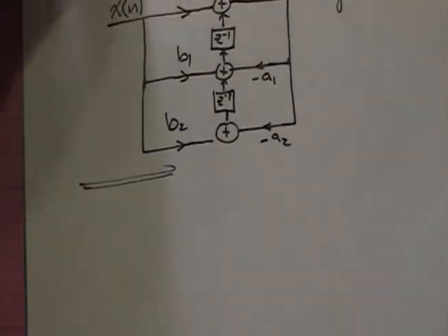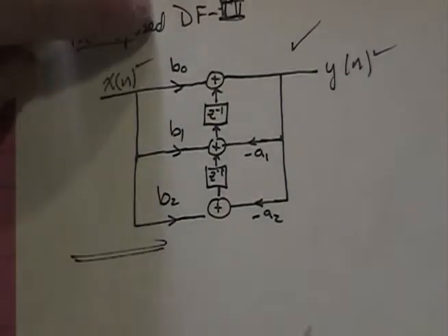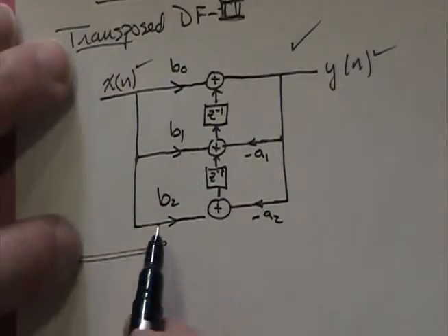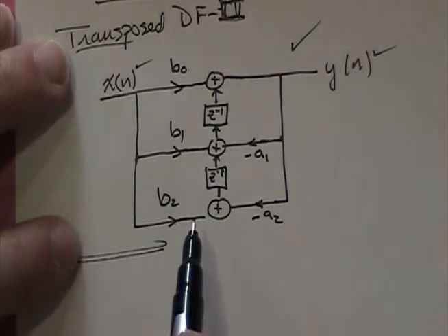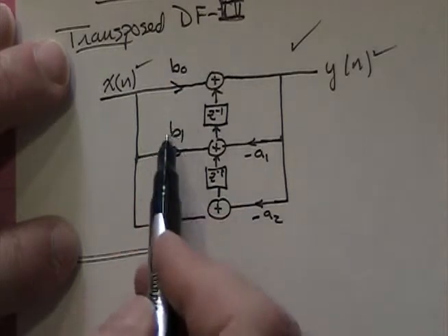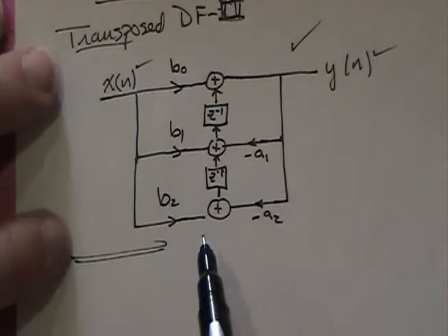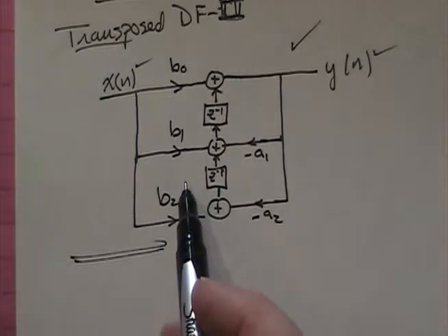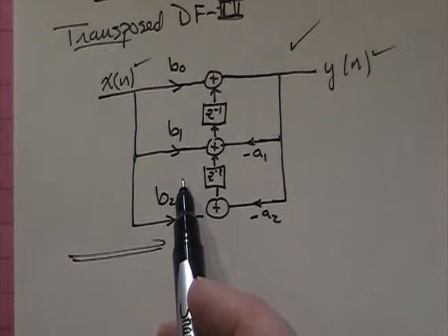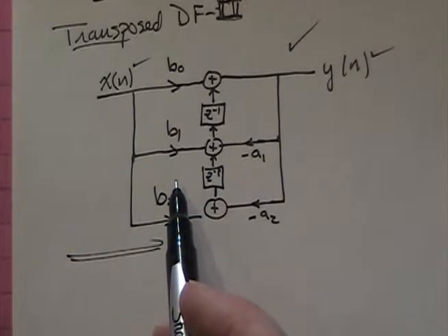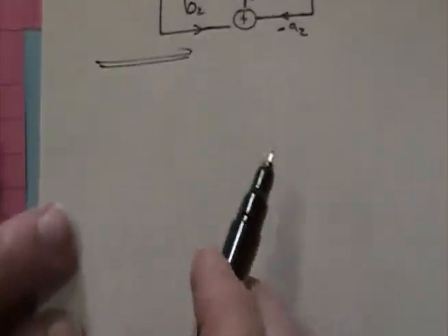There are many other second order implementations. If you run into a numerical problem, it's worth your time to go into the book and start seeing different structures. And a lot of the most numerically stable don't involve these polynomial coefficients in the filter structure at all. We round things off to make things a little bit better behaved. Okay. Cascade implementations aren't the only option.